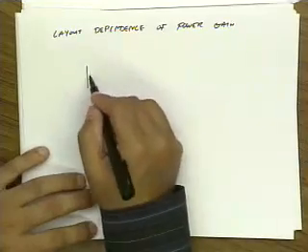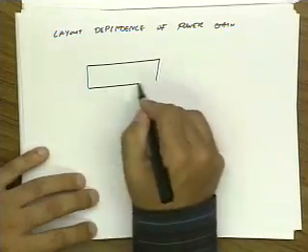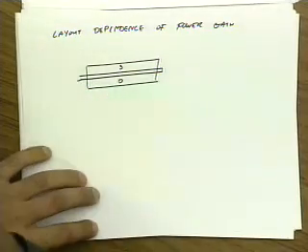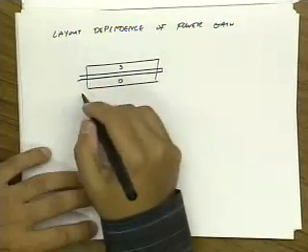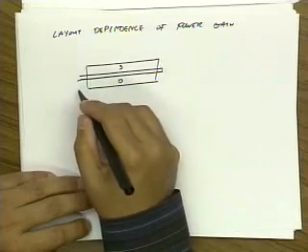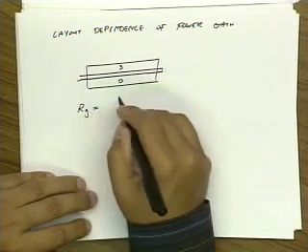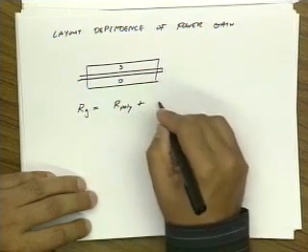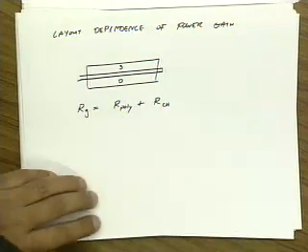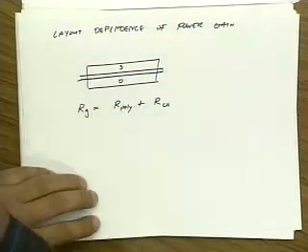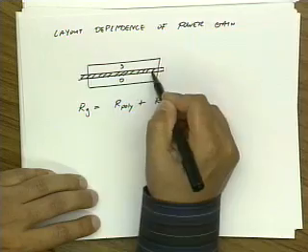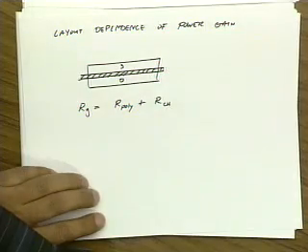So let's say you have a FET and you lay it out like this. So this is the gate, this is the source, this is the drain. And remember, our gate has two contributions. So our gate has our poly plus our channel. Now the poly resistance is quite easy to understand. It's just the resistance, it's proportional to the resistance of this gate finger, right?